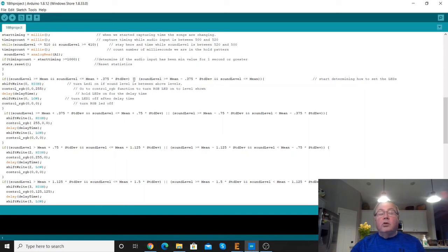We're also going to, to the right of the mean, divide that bell curve into 8 sections. And we're going to say, okay, if we're in a particular section to the left of the mean and the similar section to the right of the mean, we're going to turn on a particular LED at the output of that shift register and make it high.